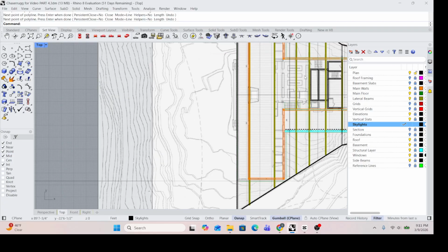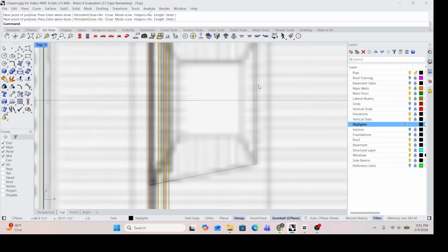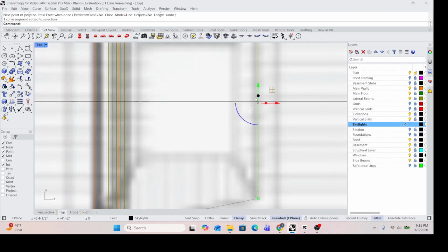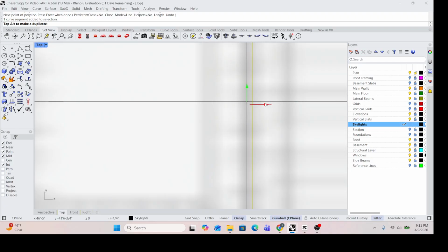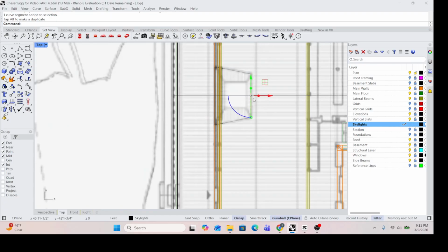And because of this other back wall close thing, I'm going to hold Control Shift and click, get the curve segment, and I just want to move that in. I don't want to mess with that back wall.